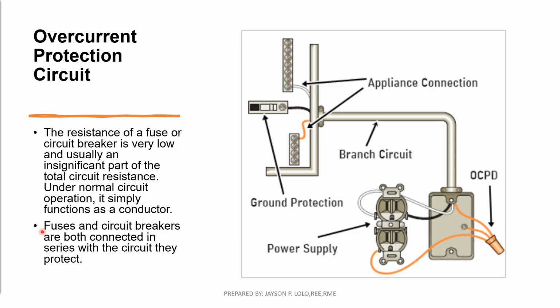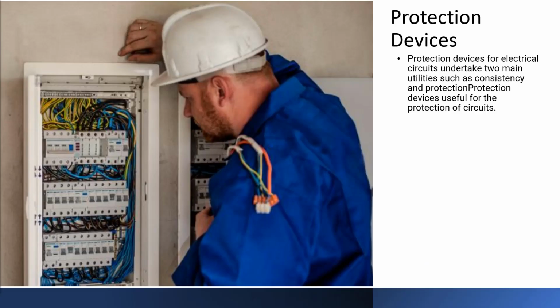Remember, they are not normally capable of correcting the problem. For this reason, you will need to locate and correct the problem before replacing a fuse or resetting a circuit breaker. Protection devices: in this, protection is assured by detaching the power supply, and it is overcurrent protection.